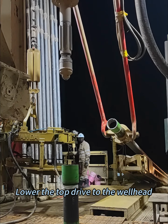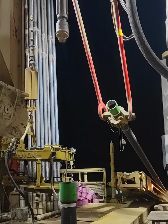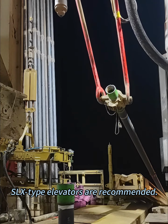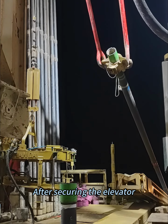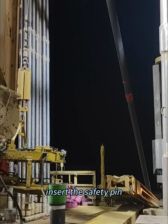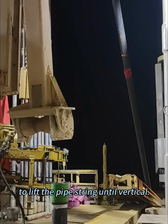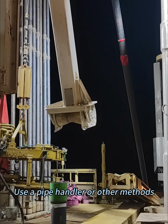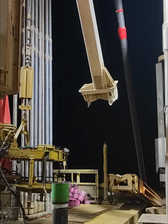Lower the top drive to the wellhead, where the elevator grips the casing on the ramp or in the mouse hole. SLX-type elevators are recommended. After securing the elevator, insert the safety pin and slowly raise the top drive to lift the pipe string until vertical. Use a pipe handler or other methods to stabilize the lower end of the casing and prevent impact.